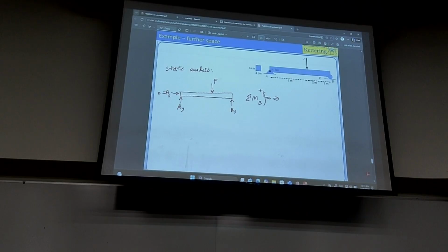For instance, the moment of AY about B. To figure out the sign, assume an imaginary pin at B, flick it with the force of interest, being AY this time, and visualize how it would rotate. Clockwise or counterclockwise? It would rotate clockwise, so make it negative. The magnitude of the moment is the product of force times normal distance. What's the distance between AY and BY?